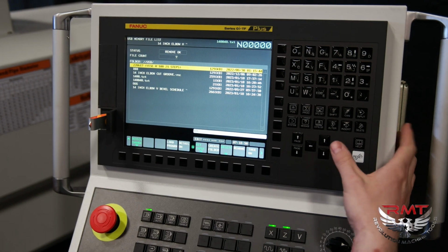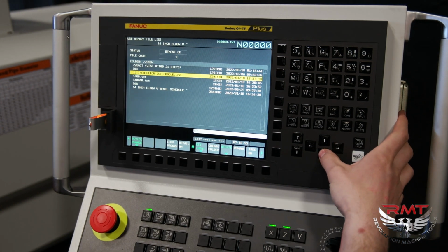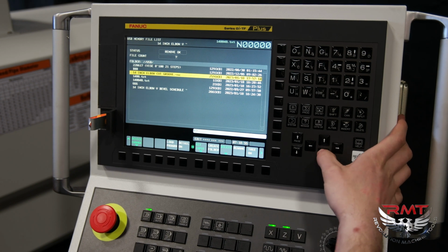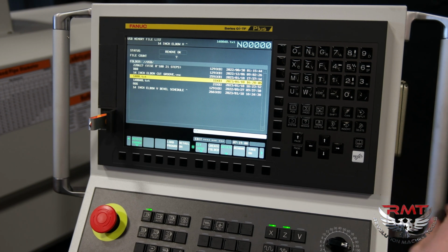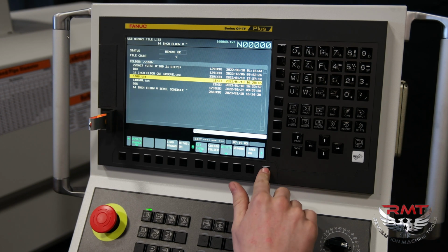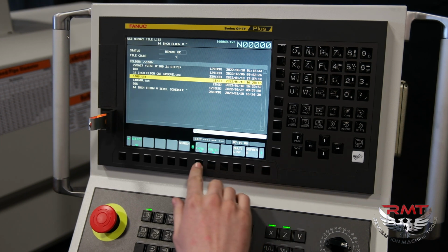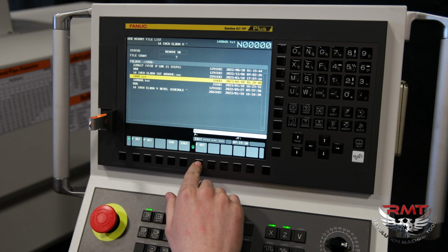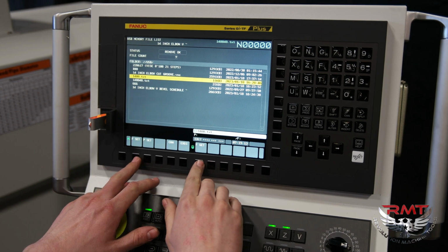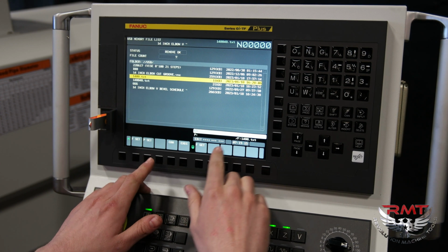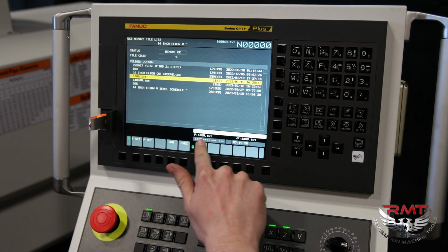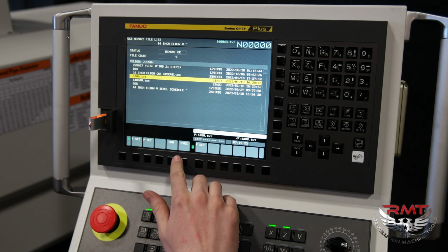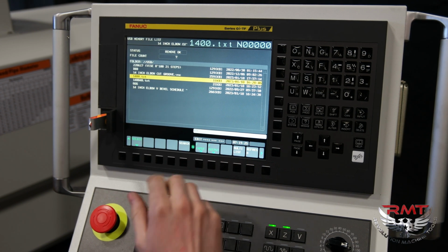This will then have a list of all the programs currently on your USB, whether you are re-downloading an old program that got tampered with or loading a new program. We will then highlight the desired program and arrow to the right until we see F input. Select that. I will then select F get, F set, which then should populate my F line, F get P set, which should populate my P line. And then I will select execute.